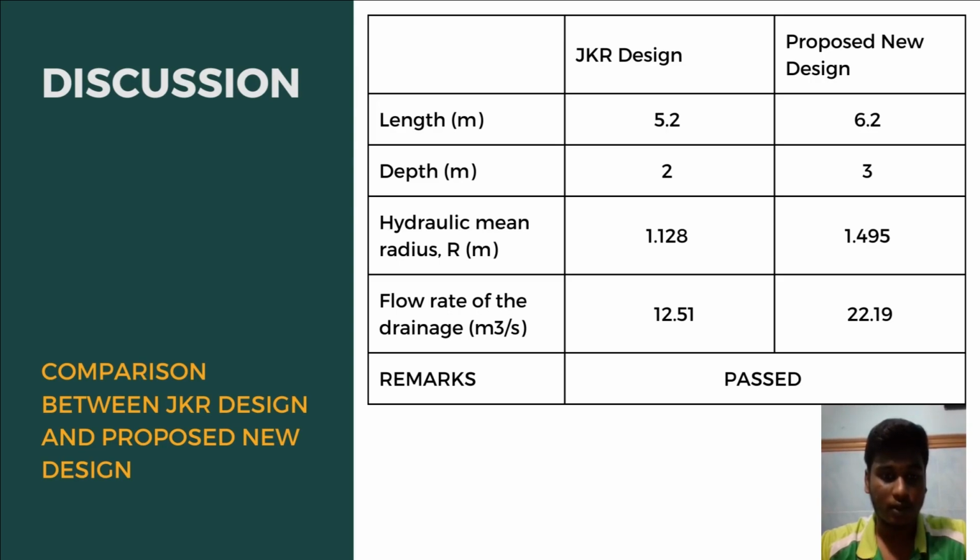The type of grass drains with short grass cover less than 150 millimeter determined the value of n as the given value, 0.035. So it is based on the value of Manning's roughness coefficient, one of the most significant parameters in hydrological calculation that represents the loss of energy in open channels, and it is also frequently used to calculate the discharge and flood water elevation.